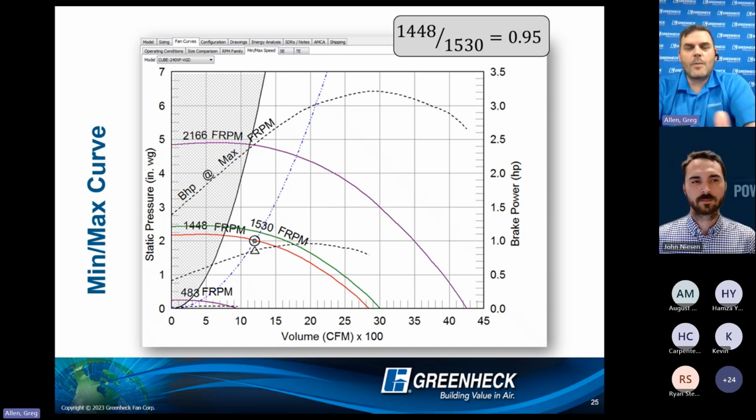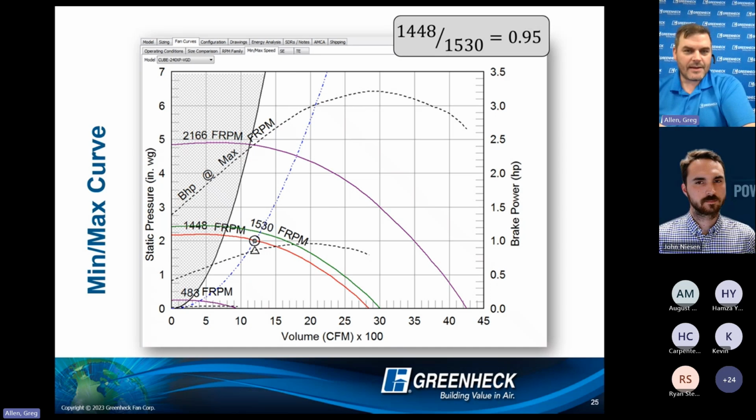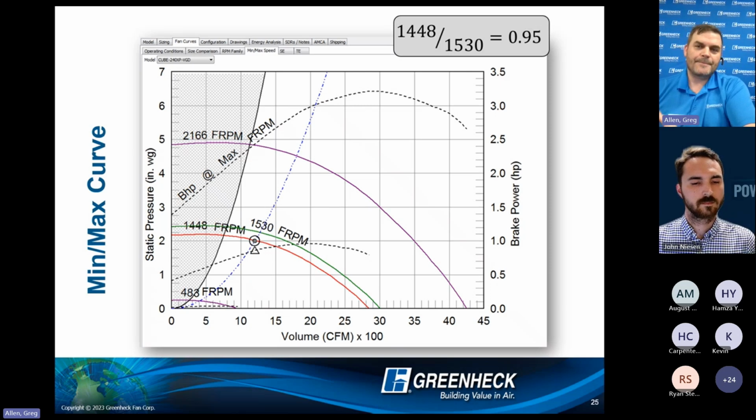Now, what that does is that opens the world to controls, right? Now I have access to, anything less than 2 volts is going to be an off command. So now I have a start stop using just a 0 to 10 and the ability to set the speed. This really opens up what type of design philosophies I can employ, whether that's different points of operation depending on criteria, whether that's working off of a thermostat or a PID controlled thermostat that's going to modulate the speed of the fan to maintain a set point, right?